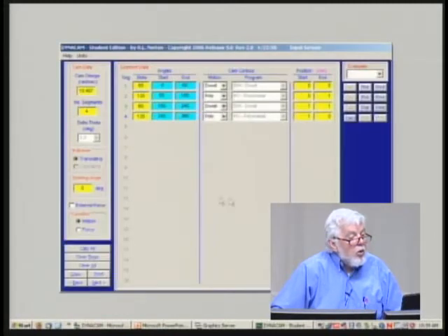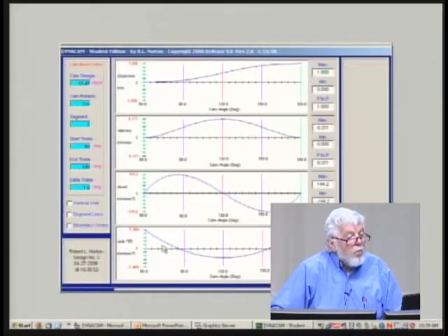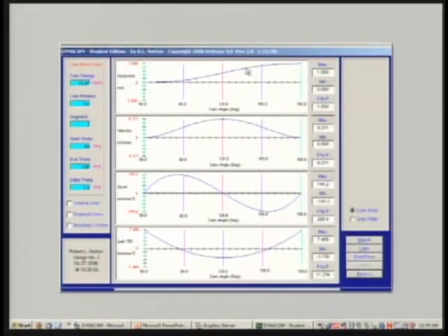That's discussed in your chapter. All right, let's see what that looks like. If I go to the plot screen, the displacement curves will always look the same because the integration smooths their differences out. Velocity looks not unlike some you've seen before. Looks a little bit like the cycloidal velocity. Here's my acceleration curve. That's where you can see the differences.